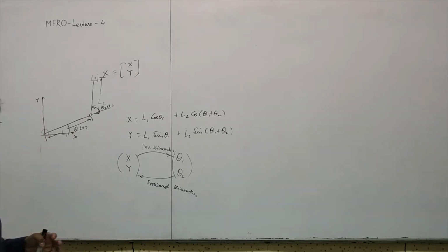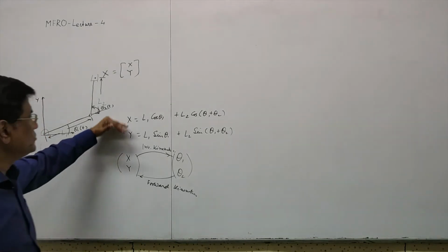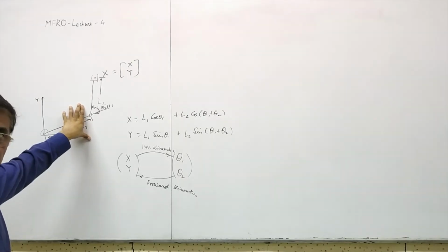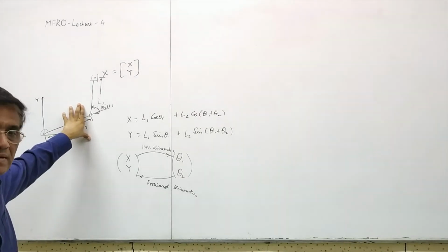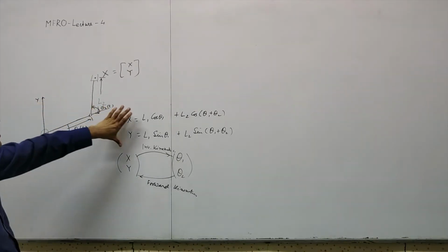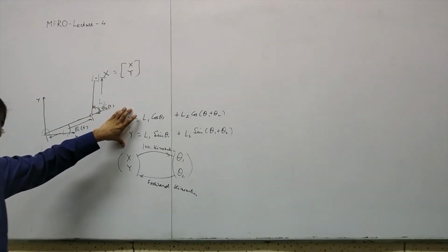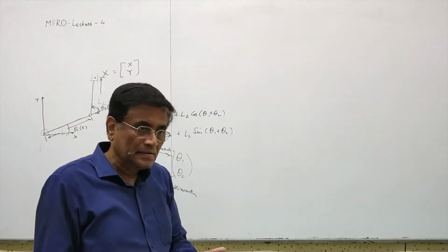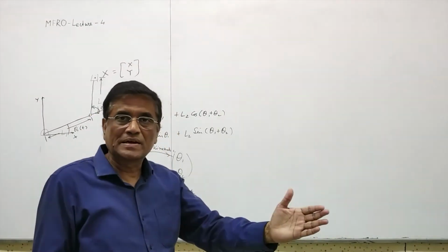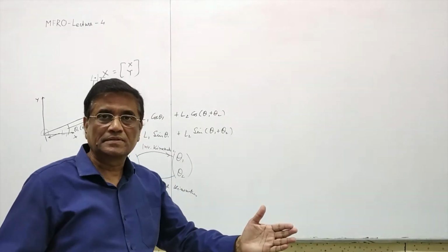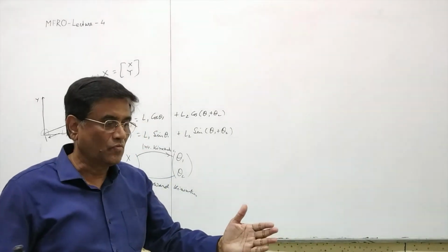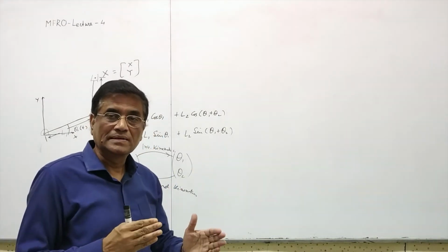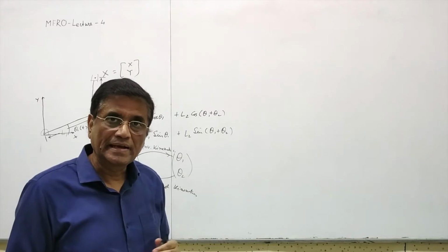So how can that happen? Out of multiple solutions, it first needs to read its home position or current position, and then it should solve the inverse kinematics problem, which will yield multiple solutions, and out of those multiple solutions, from the present joint configuration, what is the minimum movement the robot should make, that decision the robot also has to take.